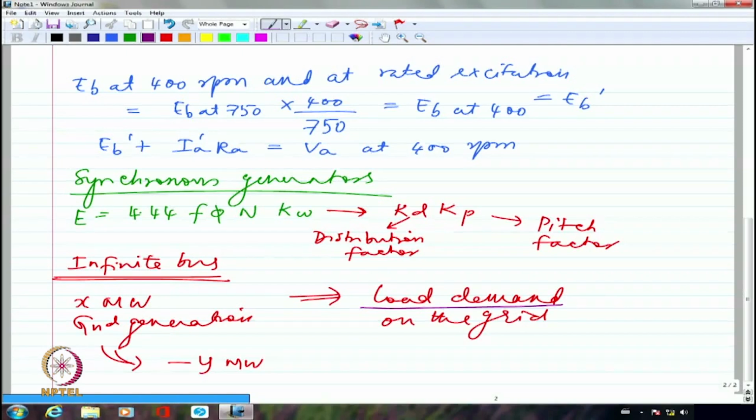The speed will not change whatsoever unless there is a power imbalance. So on the whole, whenever I connect a generator to the grid, it is a very tedious and long process. That process of connecting a generator to the grid is known as synchronization.